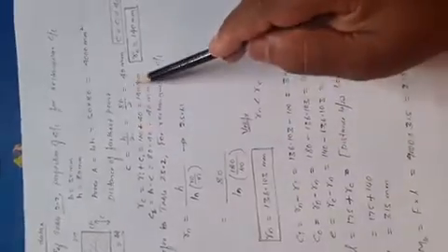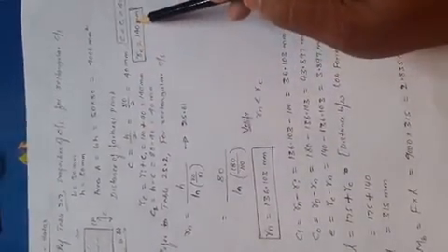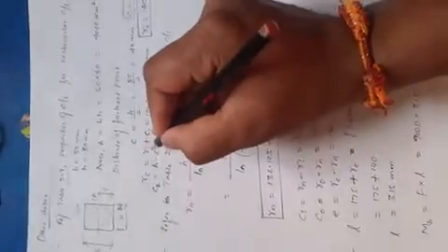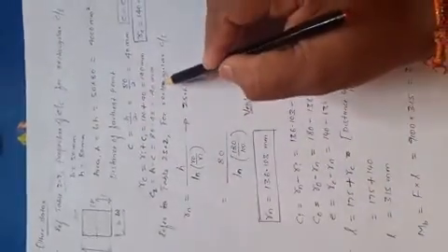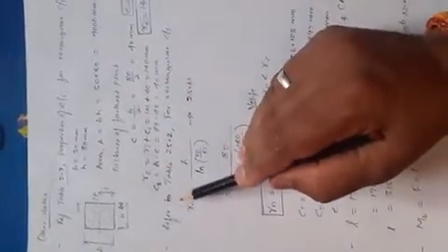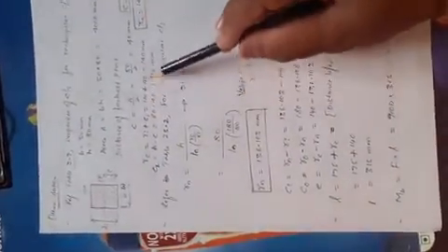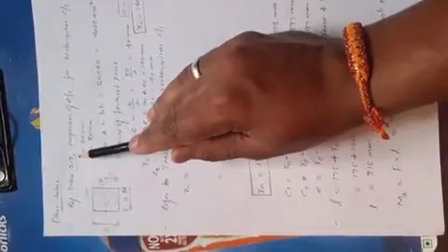Then you substitute, you get the Rc is 140 mm. Then C2, how to get C2? C2 is total h minus c1, that is h minus c1, that gives 40 mm. Now this is how you get the Rc value, C1 and C2 from Table 2.7.